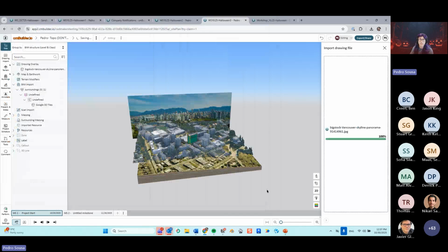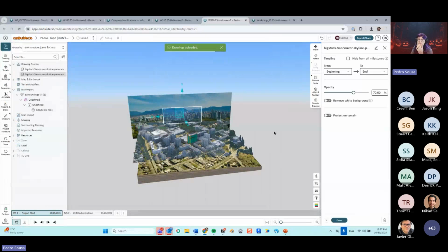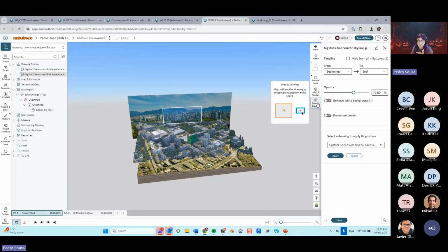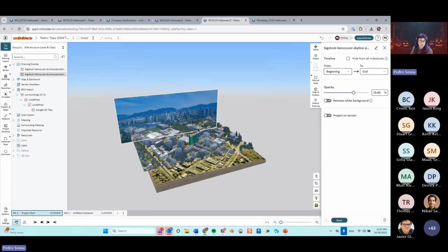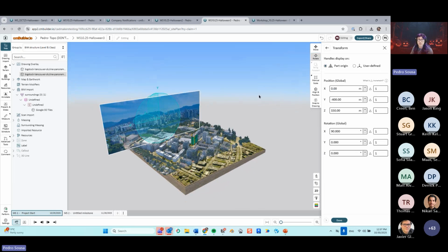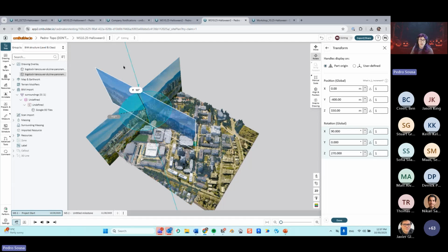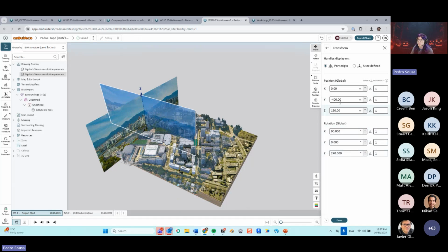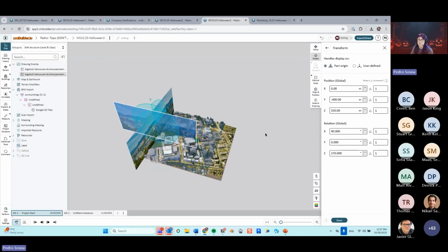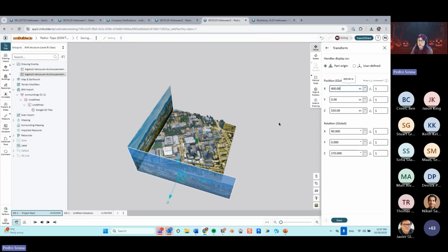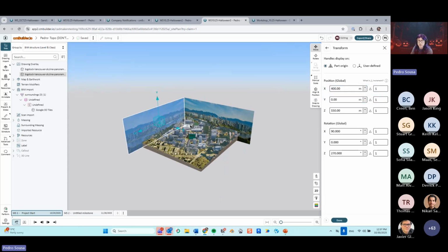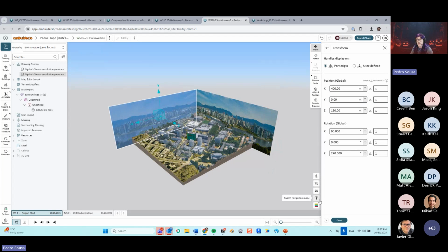to the side again, and it will be snapped over there like that, but I'm going to use this snap to drawing function so I can also get the scale, and we just position it exactly on the same spot. But now I'm going to rotate this one over here like that. The positioning I'm going to use is roughly the same, but in this case, I'm going to put the Y to be 0 and the X should be 400. That way it will now snap to that location and I get my square correctly done.